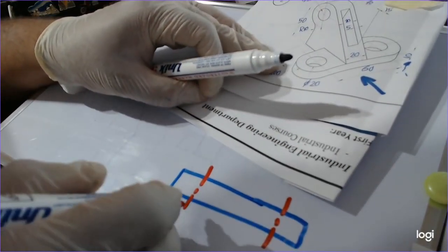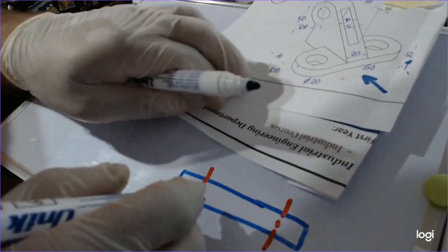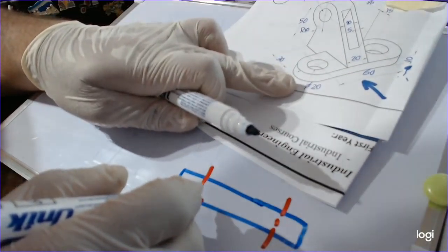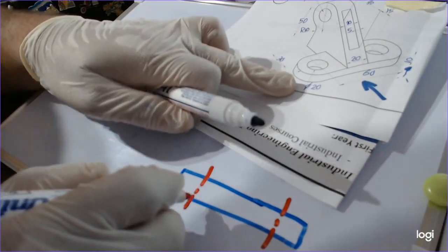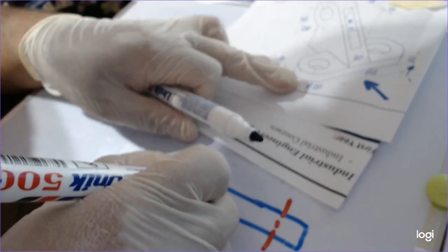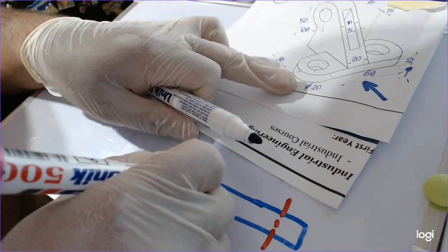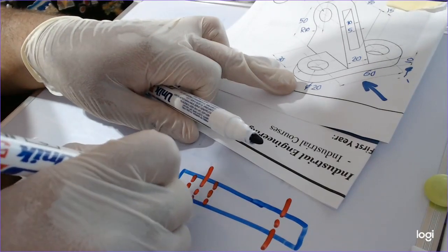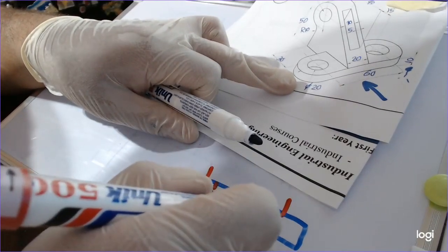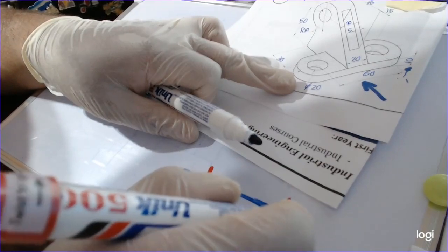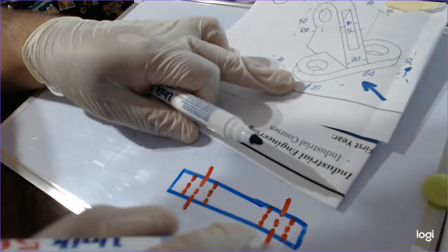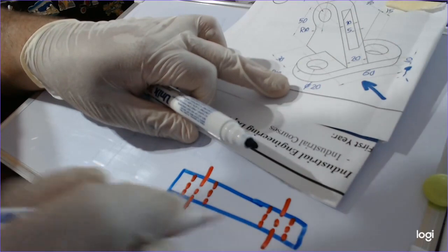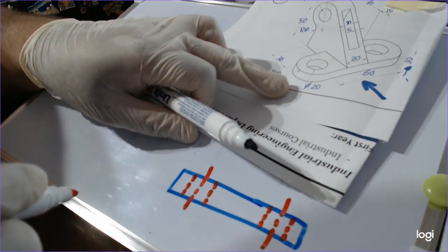Around this center line, I'll draw the dashed lines of the holes. So the holes will be 10 and 10 because the hole is phi 20 millimeters. So I'll go 10 to the right and make a dashed line here, and the same for the left, the same for the other side here, dashed line here and there, with 10 millimeters all around the center line. Okay, then